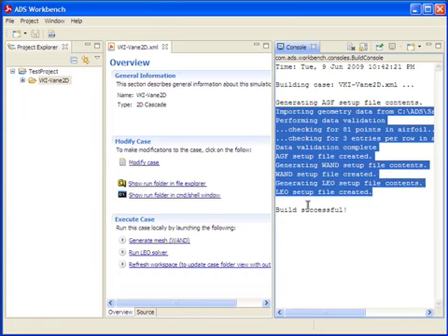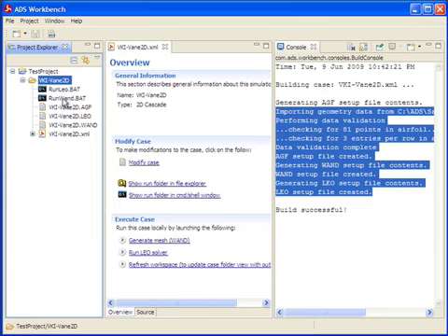One way we can tell the build is successful is by taking a look at the case folder that we created called VKI Vane2D. Sure enough, we see a number of files here: the case file, which is the XML file, the 3 setup files required by LEAP and WAND to execute, the aerogeometry file, the LEAP file, and the WAND file, and the 2 execution scripts, runleap.bat and runwand.bat, to invoke the solver and generate the mesh, respectively. Now, if you're running Linux, you won't have bat files, you'll have .sh files, but it has the same purpose, and that is to invoke local execution of your simulation runs.